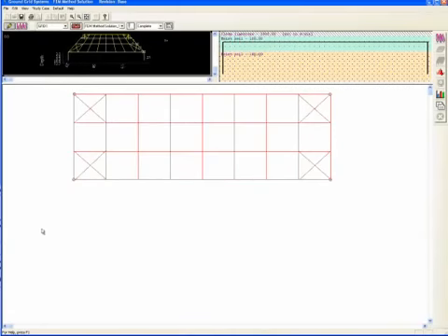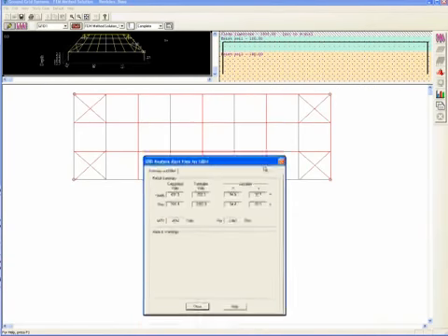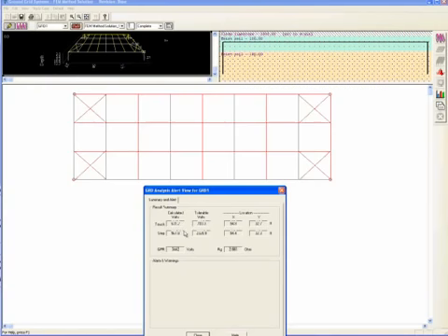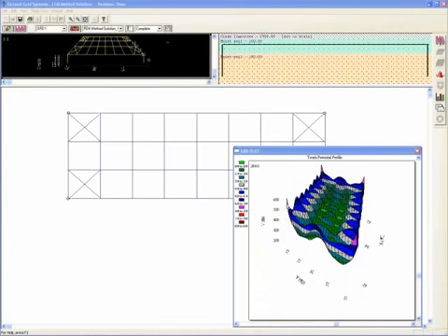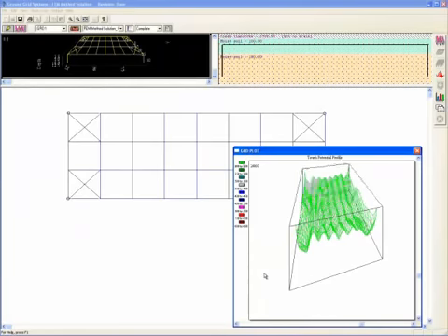As a solution with the finite element modeling, an engineer may now choose to use 4 sets of crossing conductors at the grid corners, which reduce the touch voltage by almost 13%, and simply resolve the issue. The touch voltage drop of the grid corners can be observed through the plot as well.